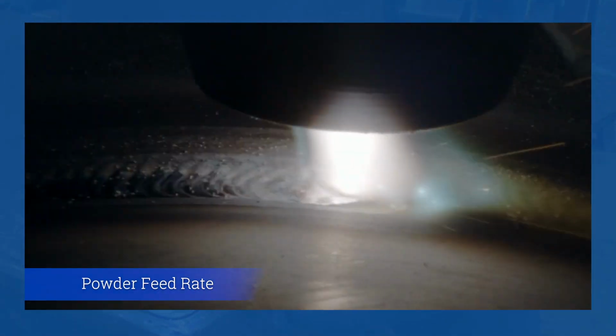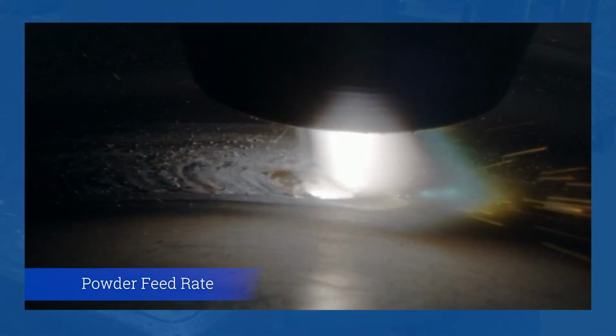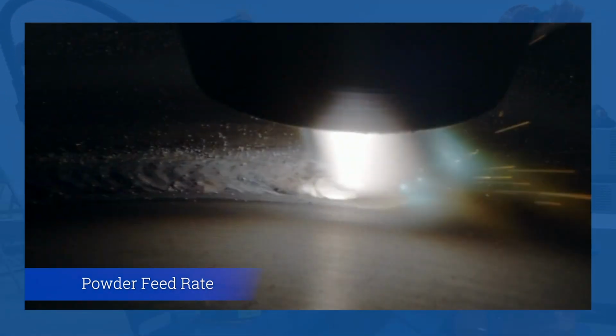Let's put it back where it should be. We're going to lose the divot. We're going to start to build a good weld again. So there's a range that will work with powder feed rate, and you need to adjust this to match the dimensional requirements of your part.